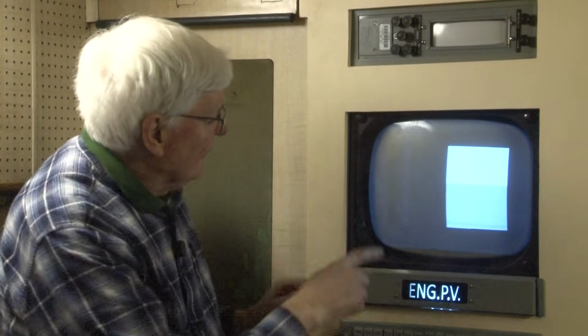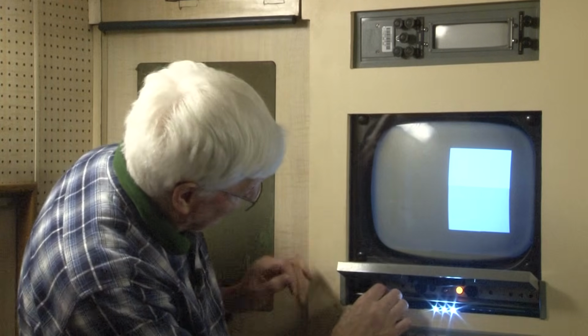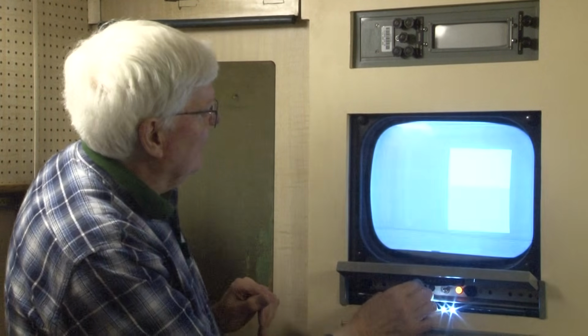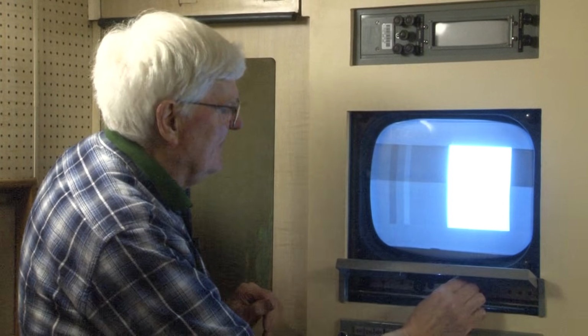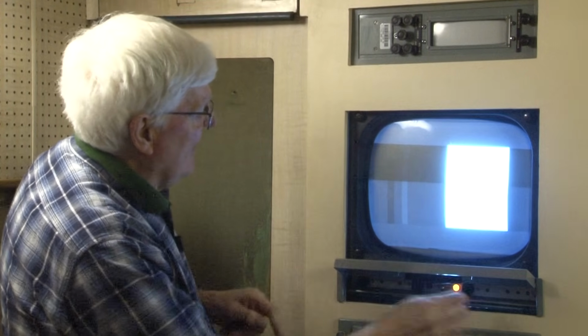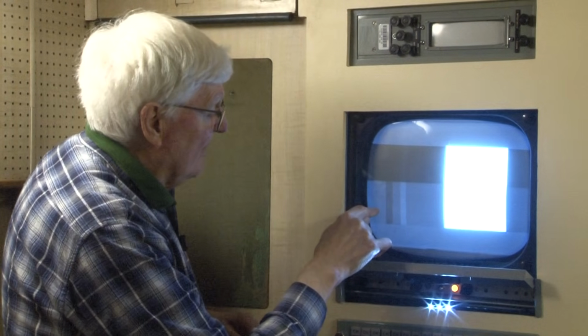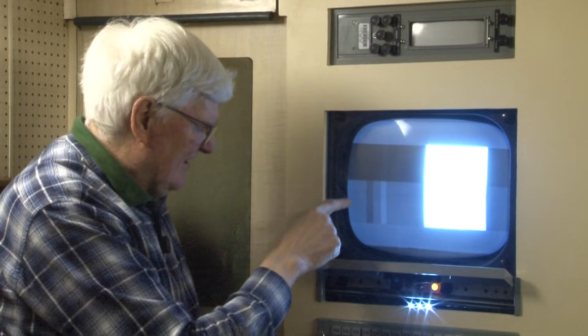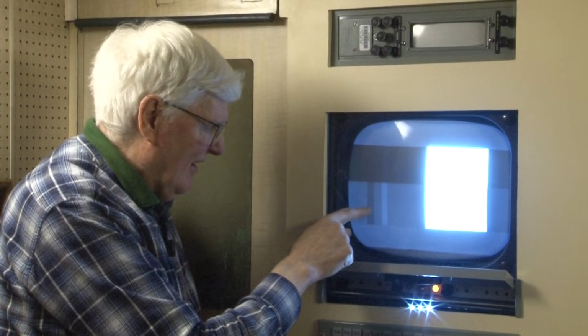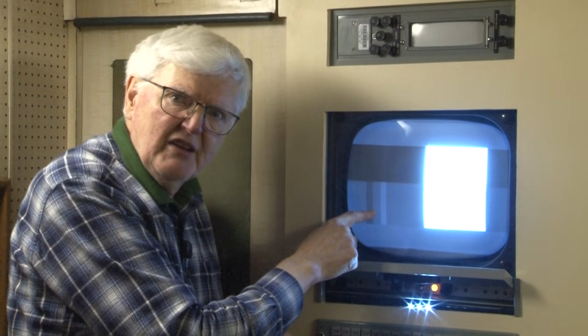There's a grey patch which encourages you to believe that the thing is relatively linear, and there's also here two very small vertical lines. Now I'm going to maladjust the monitor so that you can see that. And if I turn the brightness up and the contrast up badly, a bit of LF distortion there, but you can see here that there's a black bar and a white bar. And the object of the exercise is to set it so you can't see the black bar and you can just see the white bar.